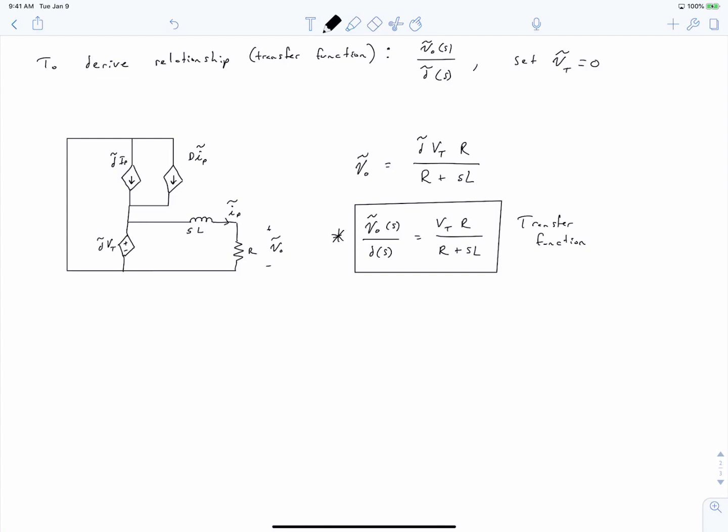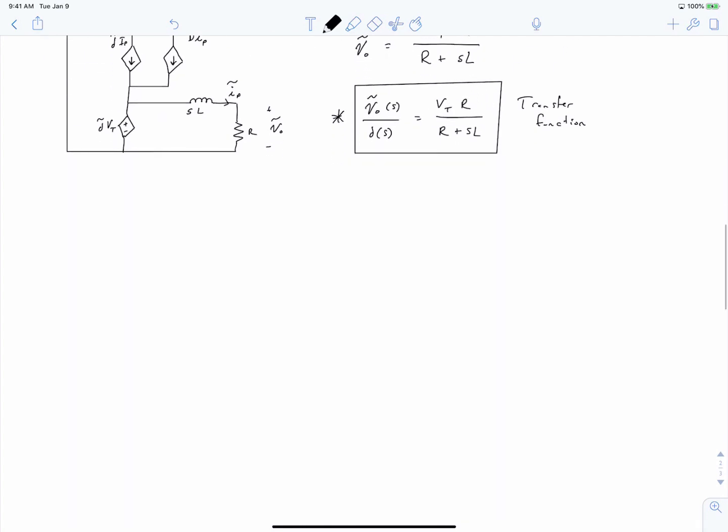So this is the transfer function that fits into the loop transfer function that we've spent the last couple of videos discussing. So let's draw how that fits in. Now we can show our transfer function for our small signal model as being V0 tilde star, which goes into a regulator block that we still don't know. This is a question mark, regulator.